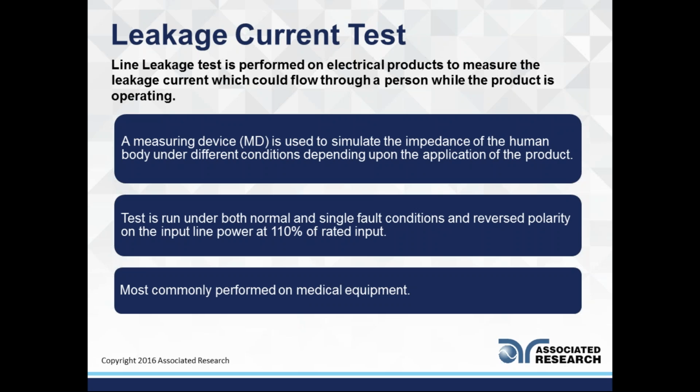Wearable technology is where leakage current testing is most prevalent. The test is run under both normal and single fault conditions, and reverse polarity. Again, I'm not sure a lot of people are certain they're running it right. These fault conditions can get very confusing.